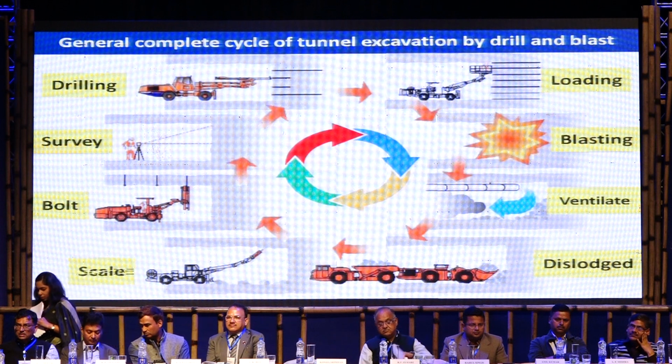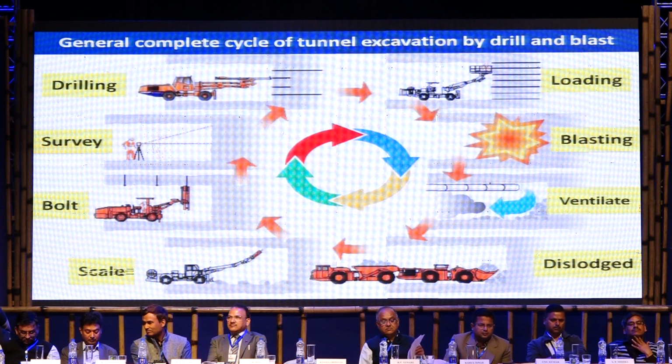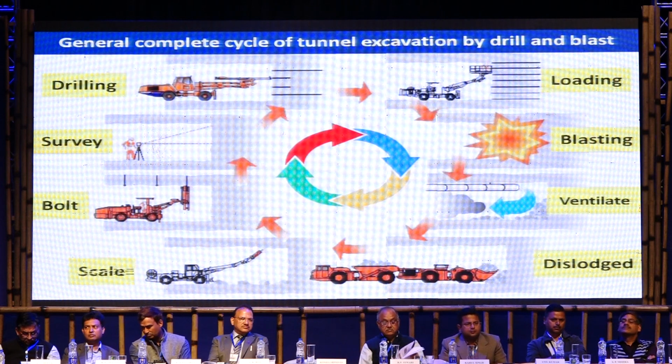So what are the sequences? First you have to do the drilling, and then loading. The sequence is there, then blasting, defuming, you have to dislodge the material, you have to do descaling, and you have to put the rock bolts here. Before that there is an initial shotcreting, because when you make a tunnel, you make an arch actually, and some portion of the arch is very unstable because cracks are generated. So you have to reconnect this unstable arch portion to the original rock mass, so that arch action is transferred to the background of the stable zone. So that is how the full technique depends.